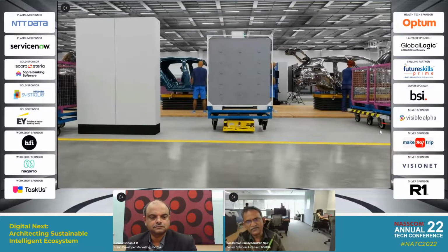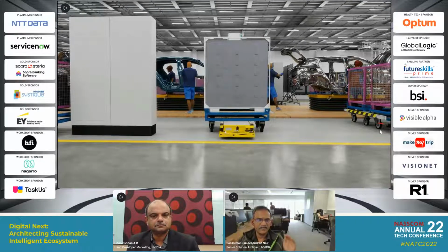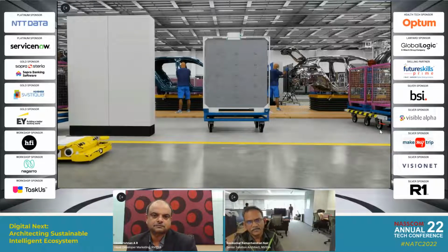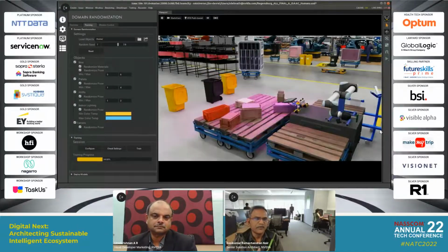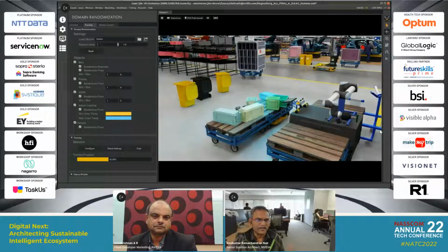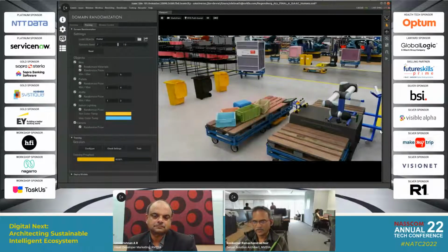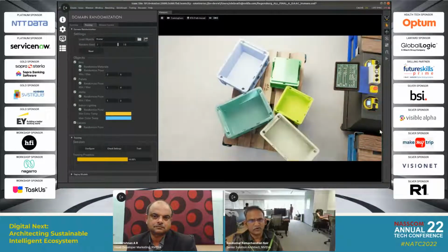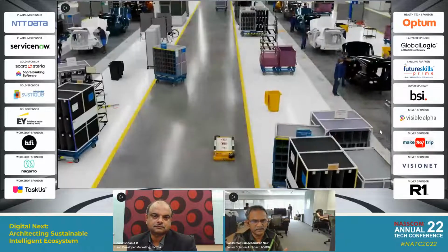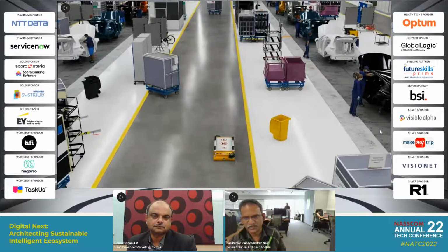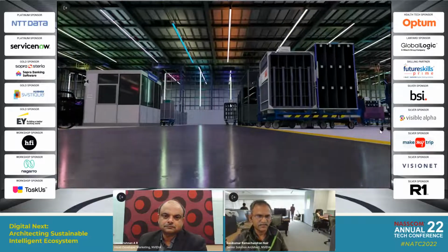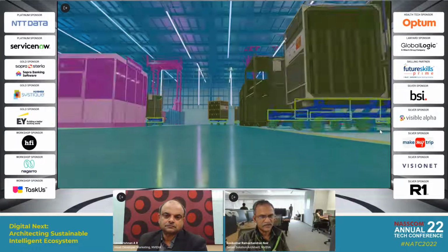And as you can imagine, this puts together a very large, very high quality, very complex world with all the components which will be a part of the actual physical twin. Now, when we do this, you need to also randomize the situations, randomize the objects in the scene, because a factory floor is not going to be exactly the same. The things lying around are not going to be the same. So there is a synthetic data generator, which could produce components and change the layout, change the texture, change the lighting, the conditions of the layout to different artificial ones.